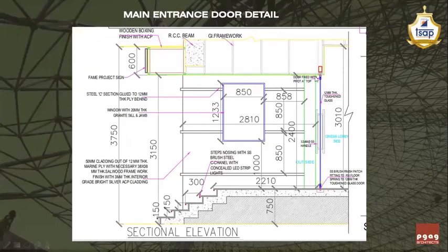The rest of the area is not a wooden false ceiling, but a gypsum false ceiling. So why are all these texts important for a contractor to know? Because he needs to know how he is going to execute this false ceiling at the main entrance. Whenever you show GI framing and wooden framing separately, and you have different finishes for the two ceilings, you are supposed to give a groove in between.